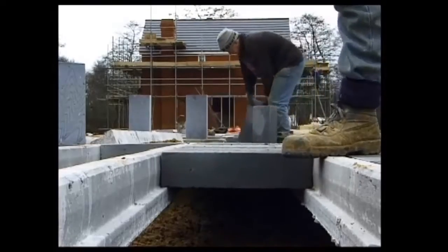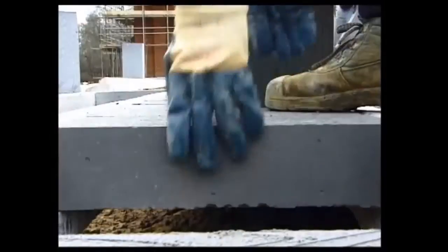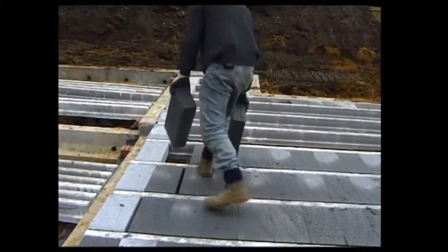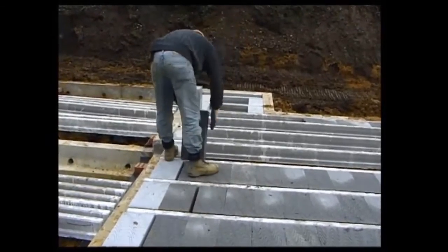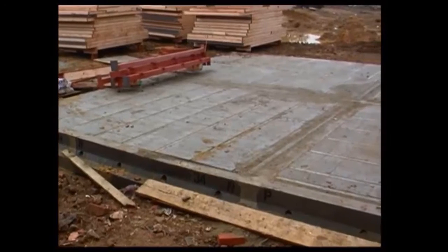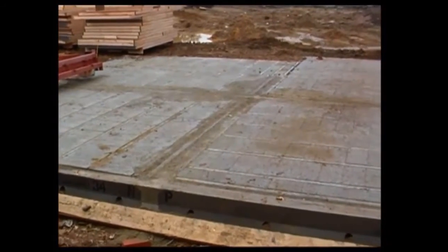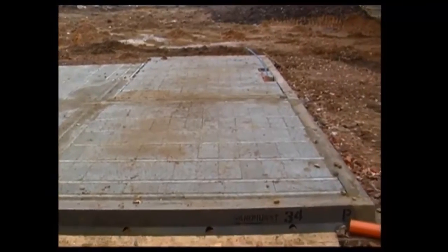These floors usually comprise a series of precast beams supporting an infill of lightweight concrete blocks. The construction is very quick, and unlike traditional wet concrete floors, it's not affected by extremes of weather. The beams and blocks are grouted to tighten up the floor, help spread loads, and to provide a barrier for drafts and vermin.